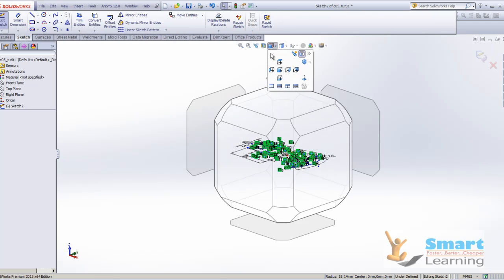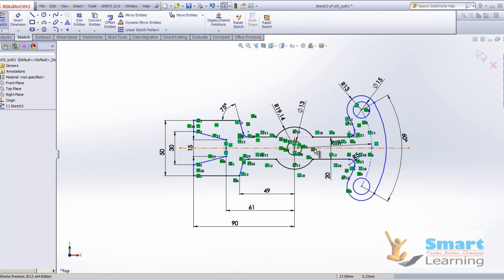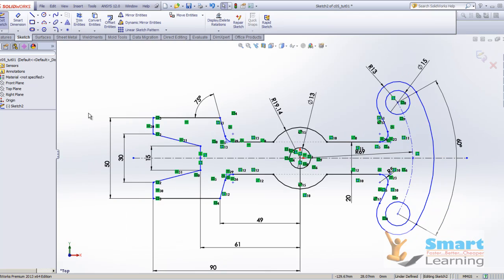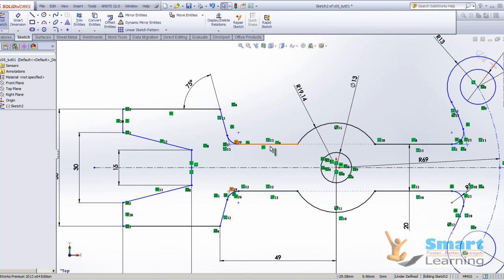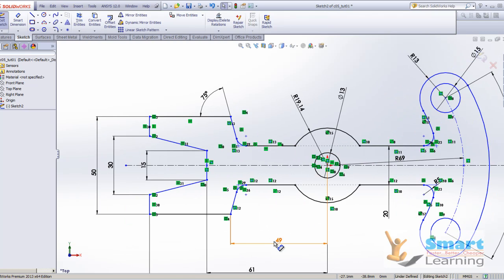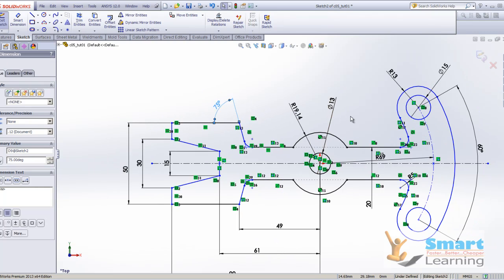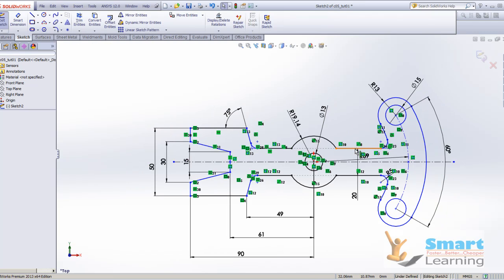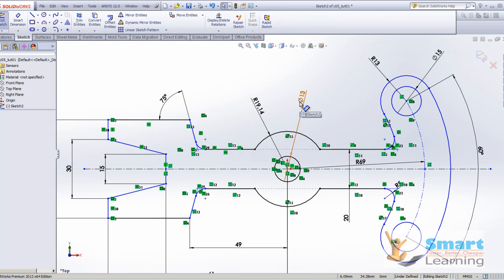So I will just align this with respect to my required views so that you can clearly see all the detailed dimensions. So you start creating from scratch and take the center line, and after that you create your basic rectangle, and after that you add these circles at the requisite distance of 49 from this corner. So once you place these circles, you will be able to capture the details about the inside circles diameter and outside, and after that you can create this feature.